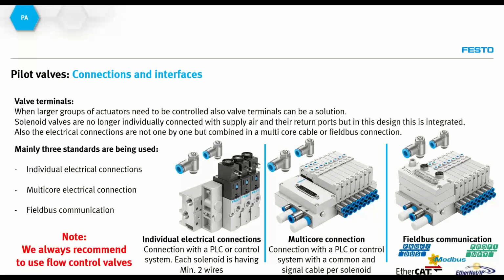So these are mainly the different designs we can have, and like the individual solenoids we've seen just before, also for these types of configurations we always recommend using flow control valves with your solenoid valves to control the opening and closing speed of the pneumatic actuators.